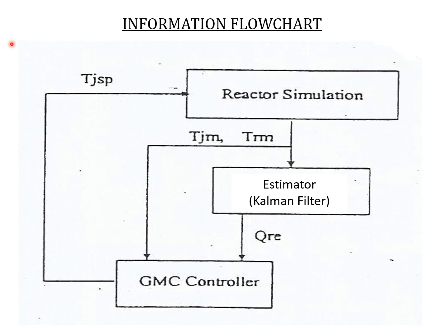Here, for the heat exchanger, which is the cooling part or the heating part, we can use PID to get the TJ to follow the TJ set point. Once you get the TJ right, it can be used with the Kalman filter to be implemented in GMC. TJ following the TJ set point means it is following the profile the GMC has come up with, the profile given by GMC.